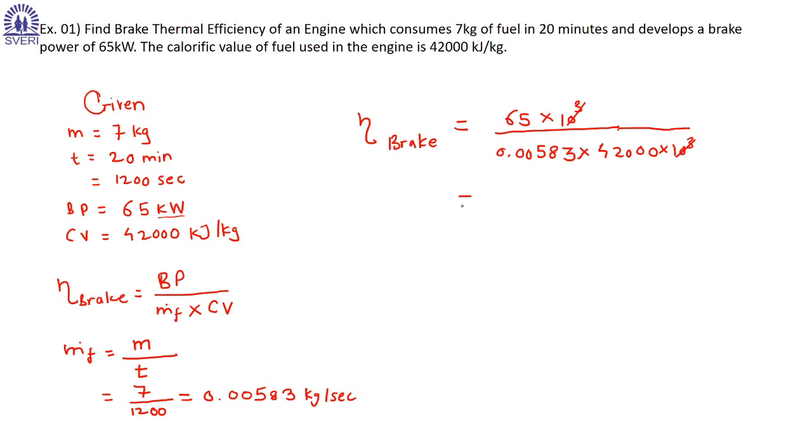Now if I calculate this, I will get a value of 0.2653, or I'll say the brake thermal efficiency is 26.53 percent. So this is how we calculate brake thermal efficiency based on brake power and the heat liberated during the combustion. We'll take the next problem.